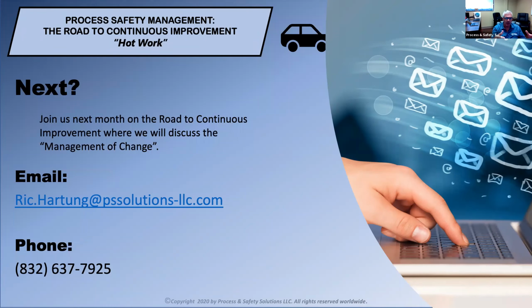So if you want to change the hot work person, let's say a person ends their day at noon and the hot work is continuing past the lunch period, as long as you have that 30 minutes before and after, certainly that is going to apply. But also during breaks, somebody has to be involved in that hot work. It doesn't necessarily mean it has to be the same person, but that same person has the responsibility of making sure they've been properly trained and that they understand all of their roles and responsibilities during that switchover.